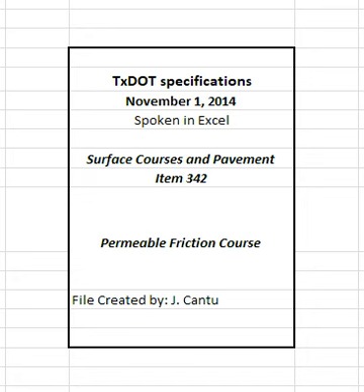Stockpile aggregates for each source and type separately. Determine aggregate gradations for mixture design and production testing based on the washed sieve analysis given in Tex 200F, Part 2.